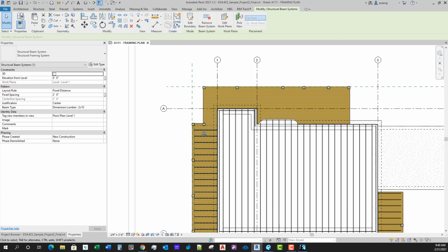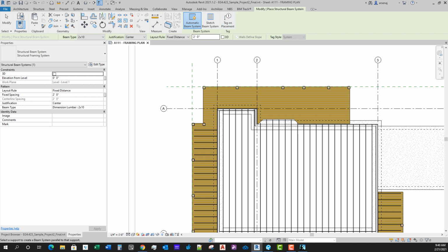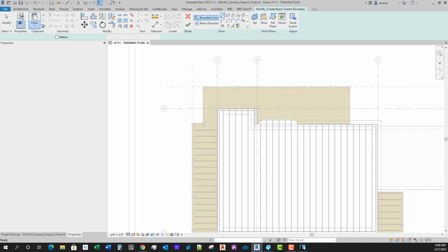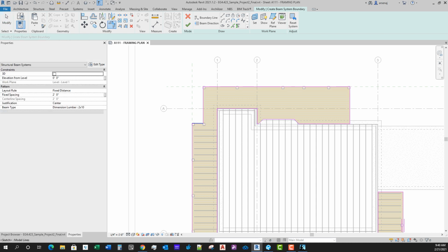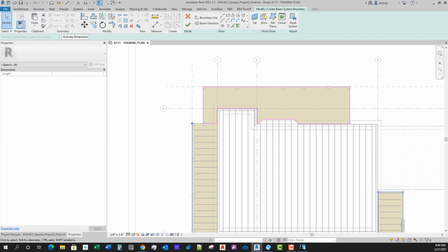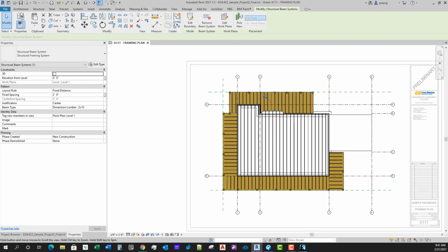And then we'll do the last one here. Beam system, sketch by beam by boundary, align to current view, paste, and then trim this last part of the deck here. We can hover over that magenta line, hit tab once and pick, and then delete it all. And remember to set the beam direction here, and then hit OK. Now I've got my deck.